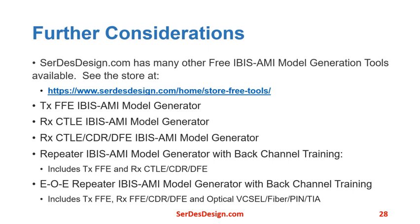It includes a TXFFE and an Rx CTLE CDR DFE as discussed in this webinar. There's also an electrical repeater model generator that includes back channel training. It includes a TXFFE generator, the Rx FFE CDR DFE, and an optical VCSEL fiber PIN TIA generator.